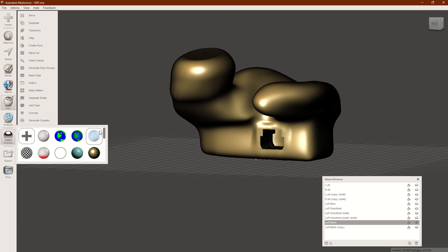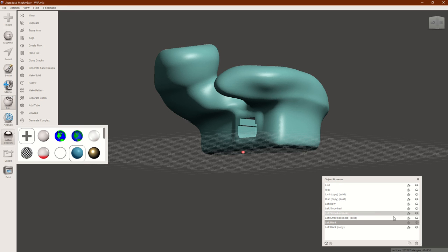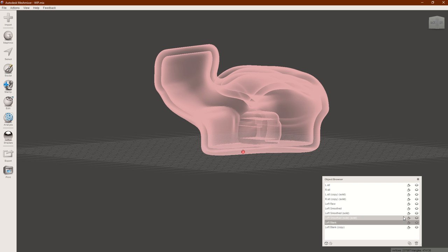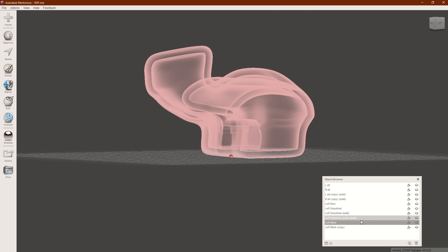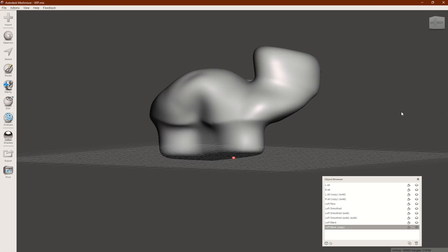But if you notice, we also have up here pretty much 1 millimeter between a working in-ear monitor and certain doom, as anybody knows that's had in-ear monitors on a stage. They take a beating. So I want to fill all this in right in the canal. The best way to do that is I'm going to give it a color first, but hide this, and then the next piece of the puzzle here is, now that that's hidden, I'm going to go back to my copy. My copy was solid, so